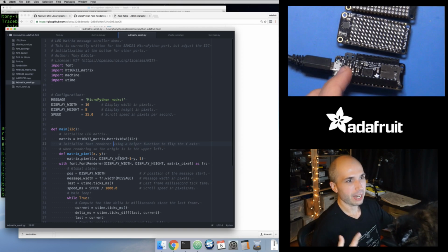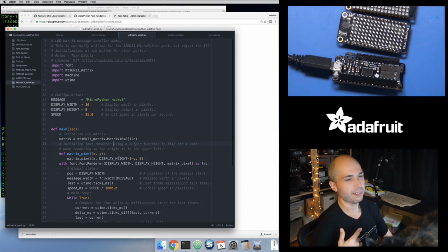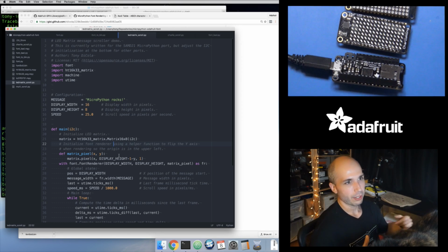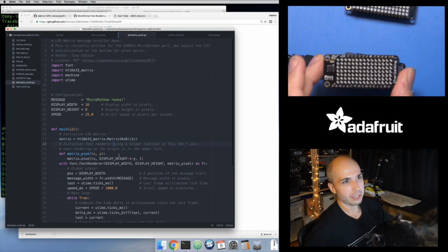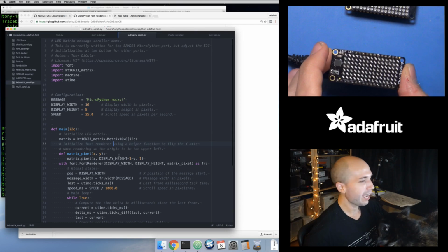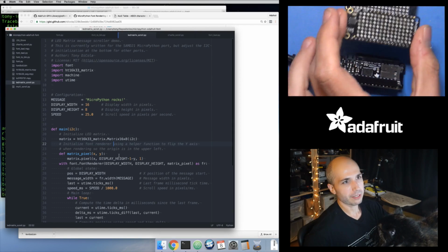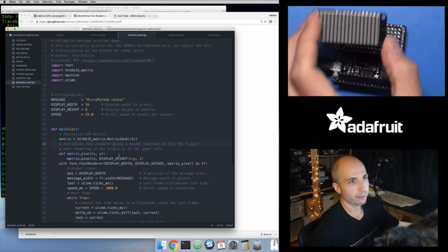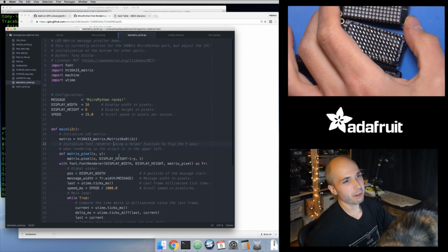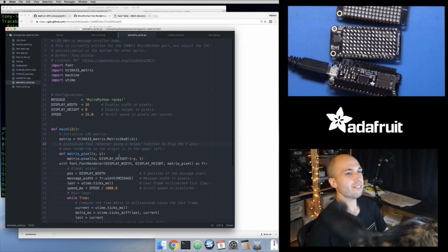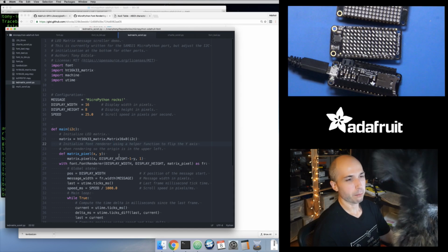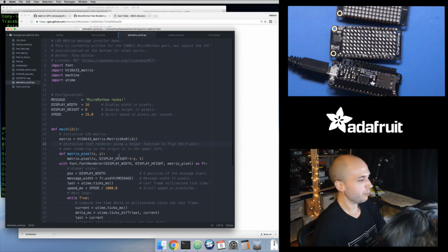And then remember, there's an I2C scan function, so I could go into a state where I say, hey, my wing was just removed, start scanning to see are any feather wings attached to the board, and it could detect when the Charlieplex wing is attached, because the driver on the Charlieplex board, the chip on there, has a unique I2C address that's different from the LED matrix. And so I think that would be a really cool demo where just based on scanning the I2C bus to see which device is attached, it will change which code it uses to scroll the message.